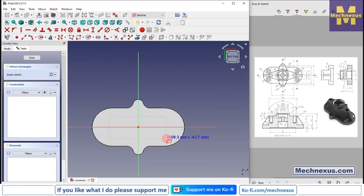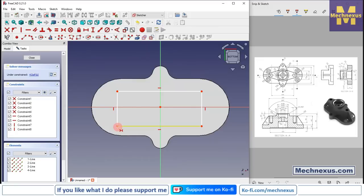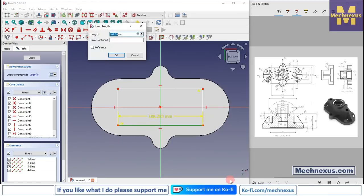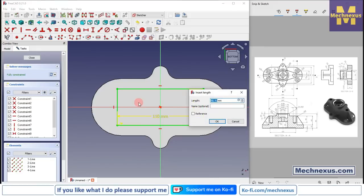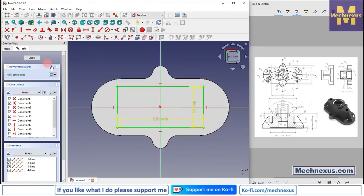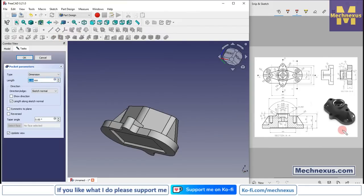we will create a rectangle, and we will use the symmetricity constraint, select this point and this origin point, and select this line and add a horizontal dimension of 110, and select vertical dimension of 55, and we will close it, select a sketch, click on extrude cut and give the value 3 mm. It is of a 3 mm cut. Here is a 3 mm, and click on OK.